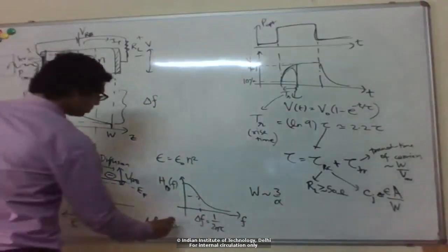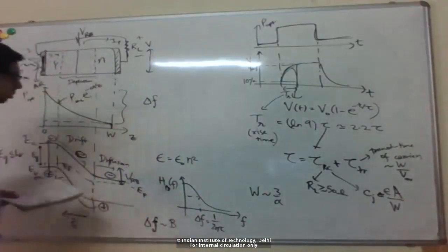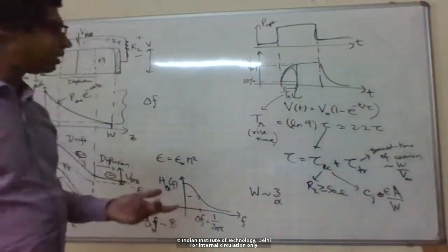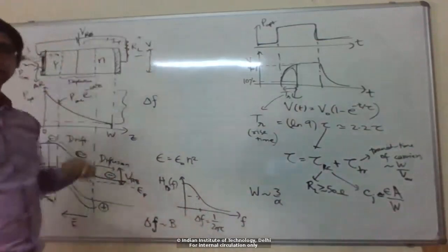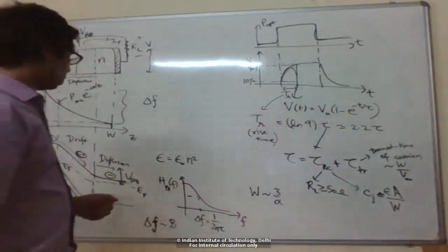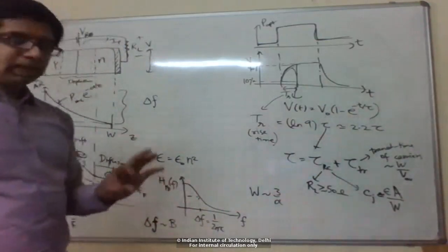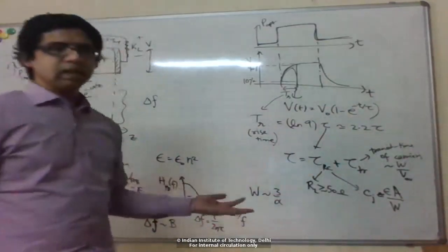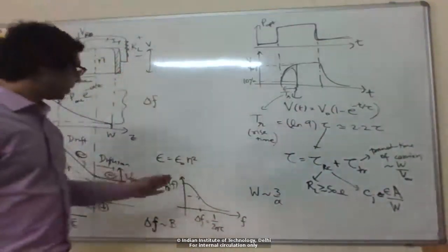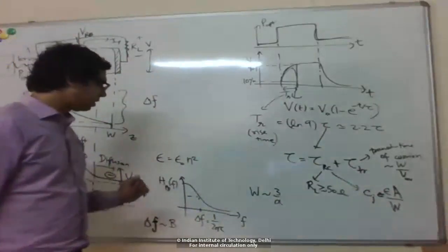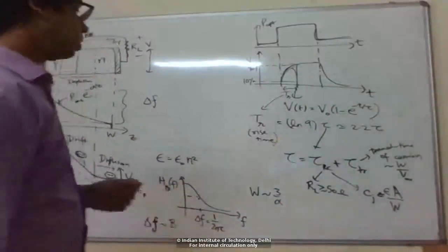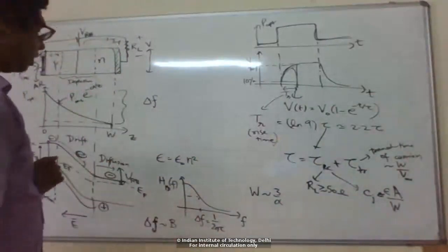Okay. So you can tailor this bandwidth. So we'll see, we can also have some additional circuitry around the detector to modify the effective bandwidth also. But anyway, it's an interplay between detecting your signal and also limiting the amount of noise that you introduce, right? So if you have a large detector bandwidth, then of course you can detect faster signals, but you also introduce more noise as well.